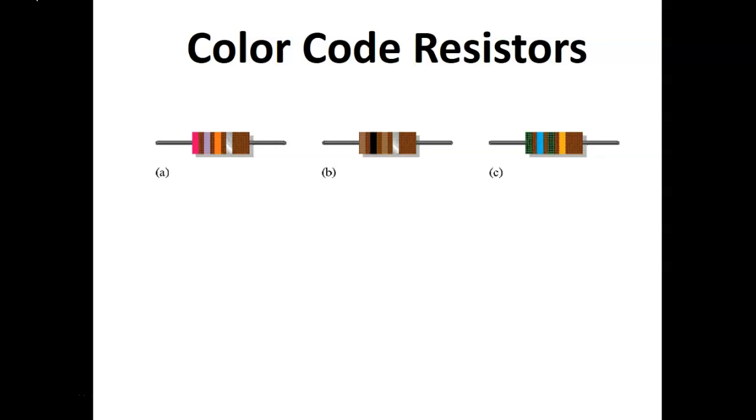Okay? Now let's talk about what that means electronically. What that means electronically is that if I need a tight run of resistance, I'm going to be real careful what I choose. If I choose a silver band, that's going to be quite a bit of tolerance. What I might look for instead is something along the lines of a violet tolerance band, which is only 1/10%.